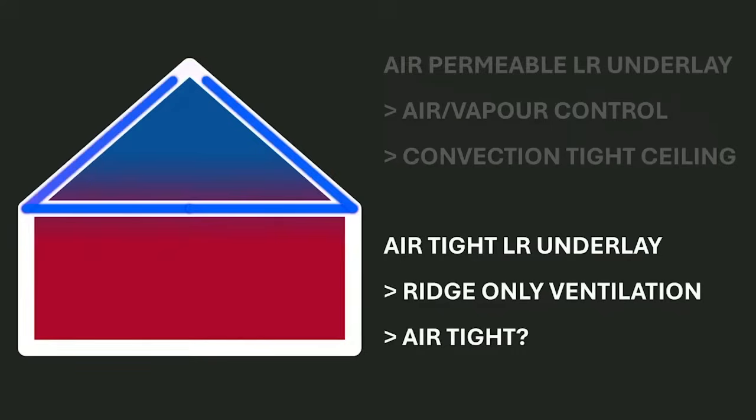Whilst it may be tempting to consider an airtight LR underlay as a good step to reducing air leakage, such membranes will often require a degree of ventilation, such as ridge-only openings. In practice, this means an airtight underlay does not necessarily mean an airtight cold roof.